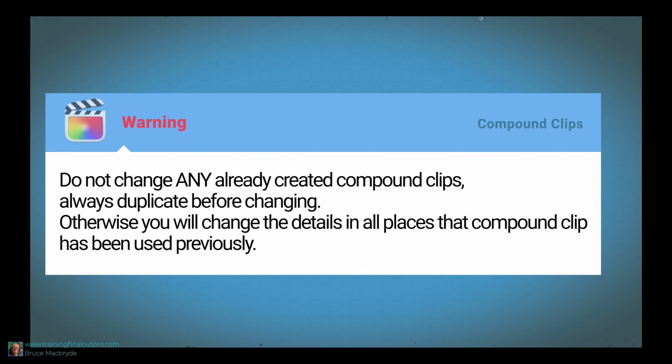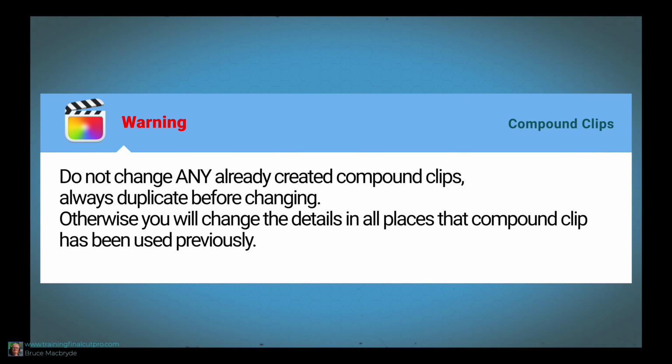And here's a warning, do not change any already created compound clips. Always duplicate before changing. Otherwise, you'll change the details in all places that compound clip has been used previously.